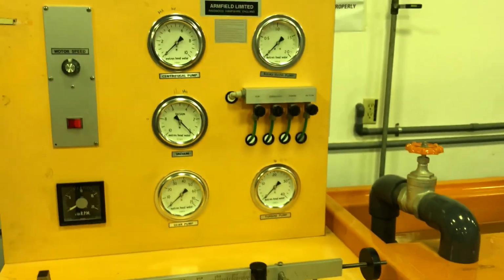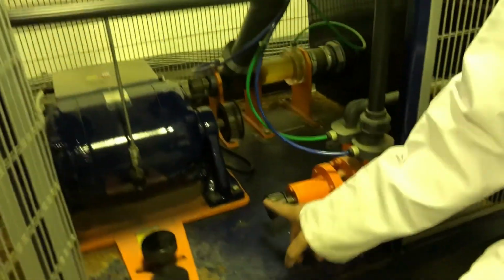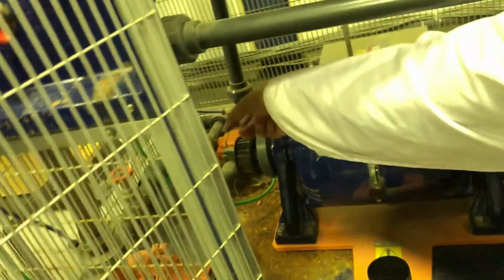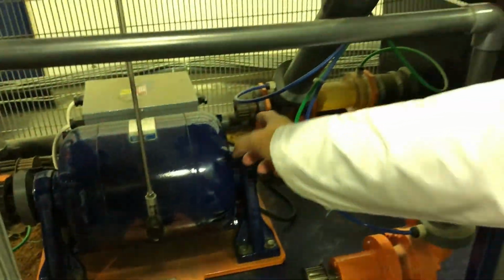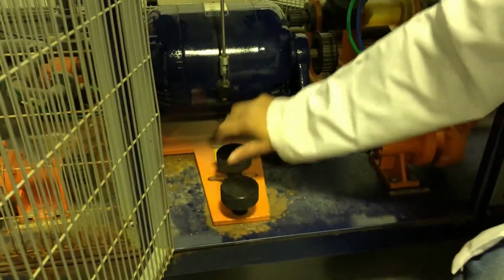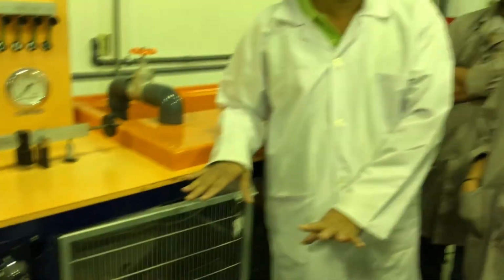So this belt we need to connect to this pulley. This is the turbine pump. Centrifugal pump here, gear pump there, and axial pump here. We need to connect by this belt. Now first don't connect the belt. Tighten this screw and run the motor with no load. Means the electric motor is under no load because we removed the belt.